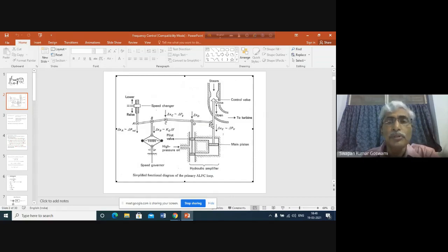Because for moving point E, you have to move the main piston either upward or downward. Since we are not doing this, since the oil here is at steady state, quiet and not moving, it is filled, and the high pressure oil pump is maintaining this pressure here, the position of E will not be changed, or it cannot be changed.